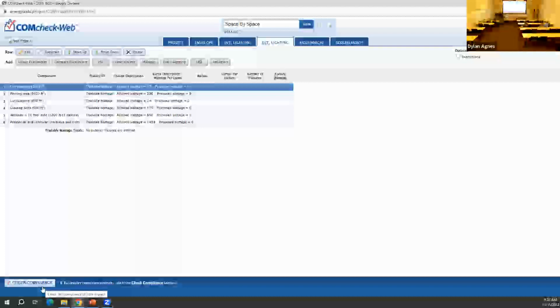Another question, because the ceiling said NA. If we have a high ceiling, I'm guessing my lumens aren't coming all the way down to my table surface, so that's a different analysis. Yeah, so you could require an exception or allowance, and then I would look at the space by space method and see if you can squeeze anything out of that.